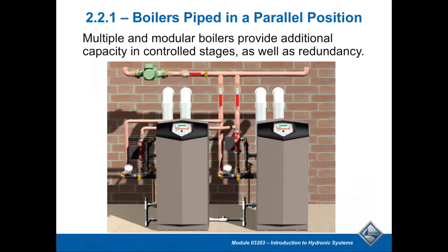So here's another beauty that also goes on in these systems. One of the things that's really nice on a lot of these wall hung boilers that are very efficient is that you're either going to vent them with polypropylene, which is a higher temp plastic pipe, or you would be using PVC or potentially even CPVC.